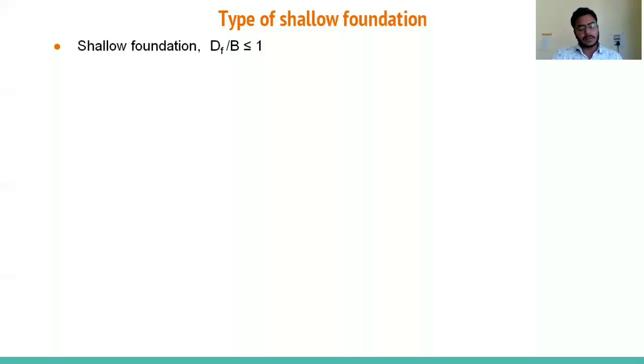It means if the bearing capacity of soil is relatively higher, in that case we can go for the shallow foundation. But in other cases also, where the load coming on the wall and column is very small, you can get the required bearing capacity at a shallow depth for that load, right? I get your point. In those cases also we can go for the shallow foundation. There are various types of shallow foundation that I will discuss one by one.